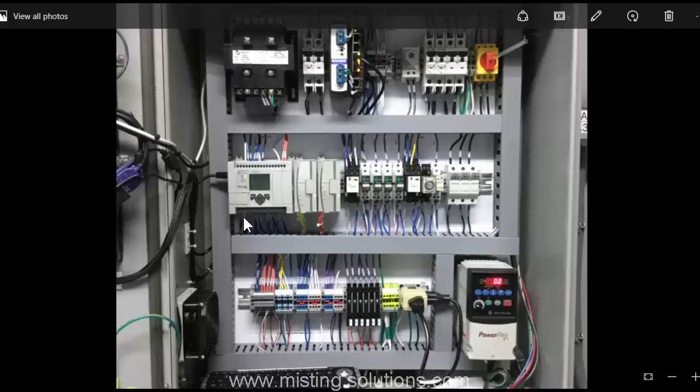Power comes in right down here, lower left-hand side. It comes from this DC power supply right here. This is 24 volts. The power supply is 60 watts. And besides powering this PLC, it does power a few other things, mainly the coils to these relays in here.